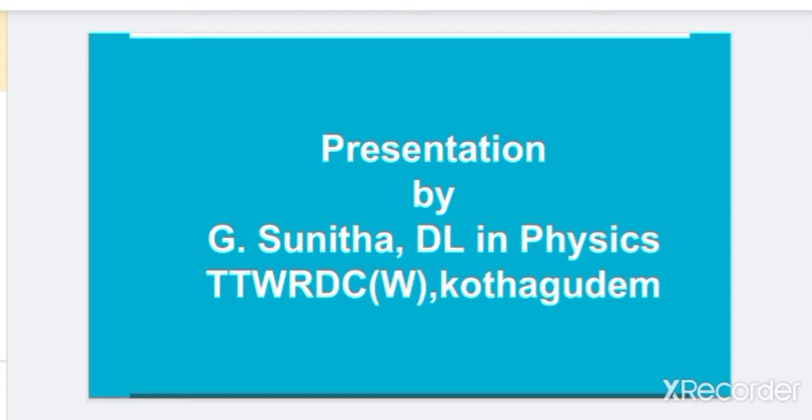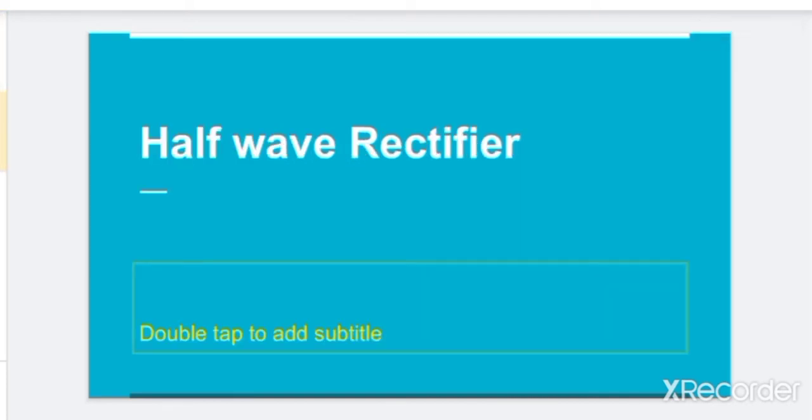So, when you think of rectifiers, we should have knowledge of alternating currents. In our houses and many industries, we use alternating current, but most of the electronic appliances work on DC. So there is a need to convert alternating current into direct current, because we need to reduce the voltage of that alternating current. So we need to use some device which can convert the alternating current into direct current. That is what we are going to discuss, the half wave rectifier.